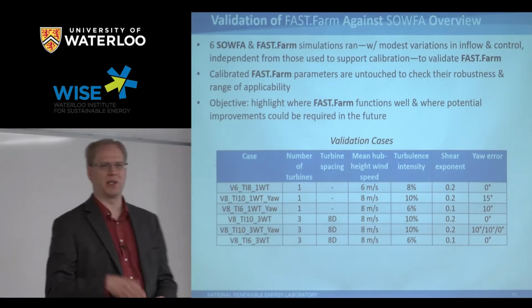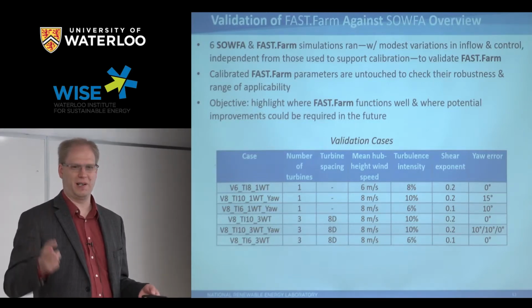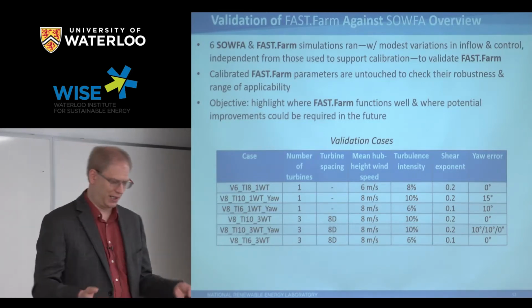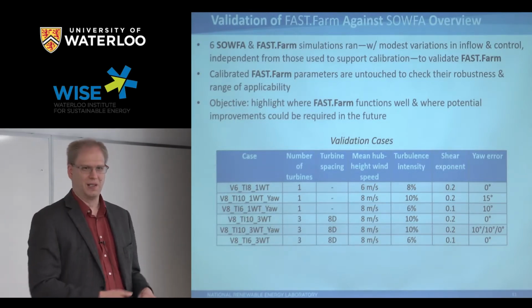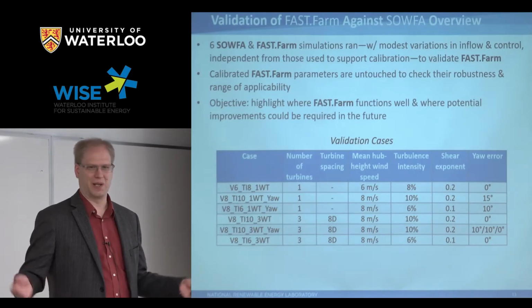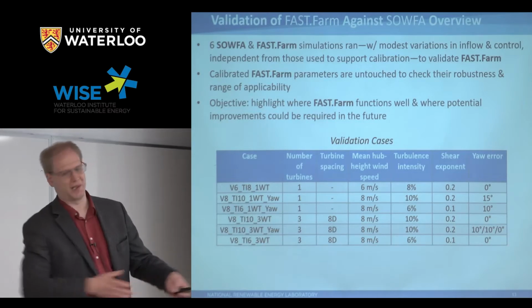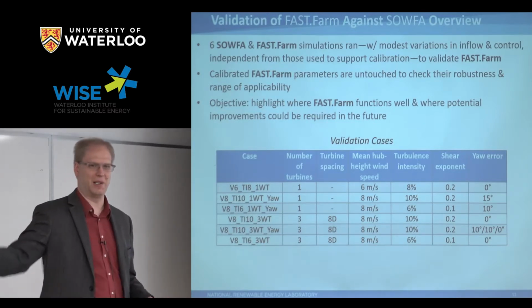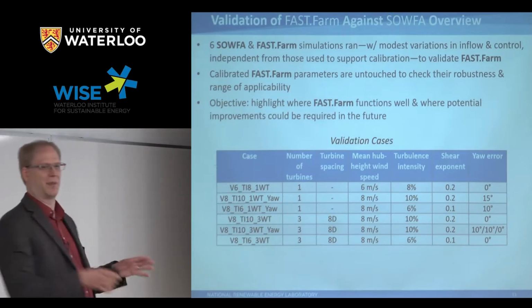And this mimics what you would do in a wind turbine simulation, like for loads analysis for one turbine. What you do is you pre-generate, you run TurbSim, familiar with that. You simply generate wind data for lots of different wind speeds, different turbulence conditions, different shears, whatever it is you need to simulate. And this database is used basically forever for every turbine designer going through that matches that set of conditions. So this is basically the same idea, but at the farm level.